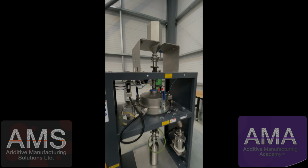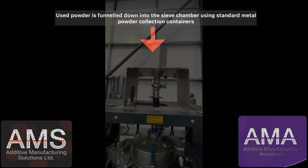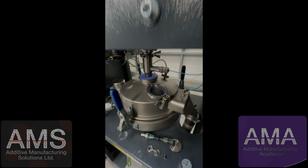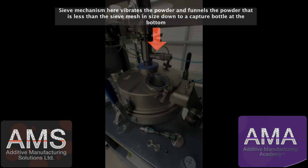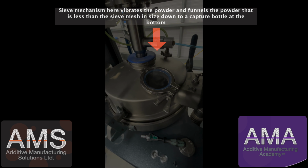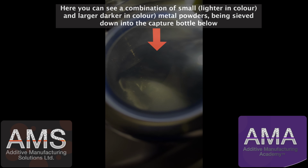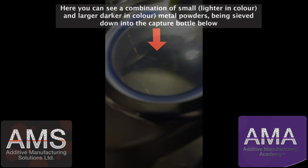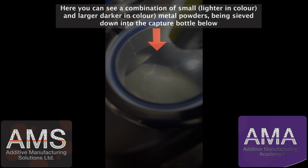In front of us here is our Russell Finex sieve. This for us is the method in which we control our powders. Powders are fed in through the top and we use a vibration mechanism to vibrate the powders through a sieve. We collect all the good powders at the bottom and the not so good powders, the large powders that have evolved or devolved through the process, are captured on the right hand side. This sieve allows us to keep consistent powder size in our process. Consistent powder size gives us a more consistent melt, and a more consistent melt gives us consistent parts and makes sure we have happy customers.